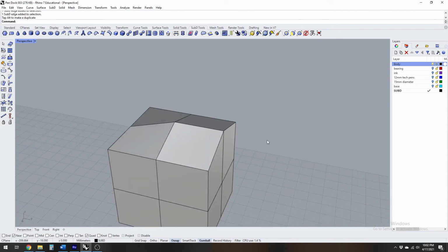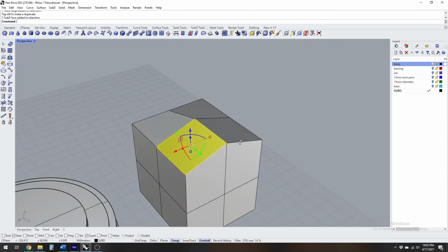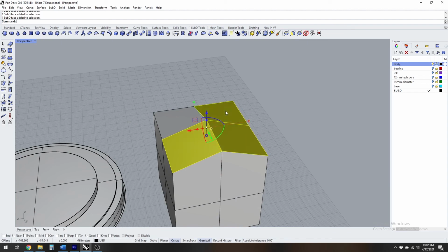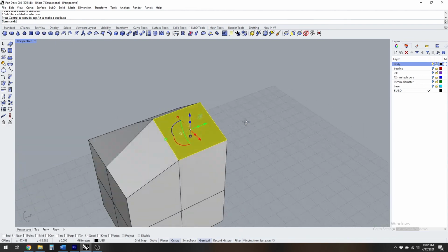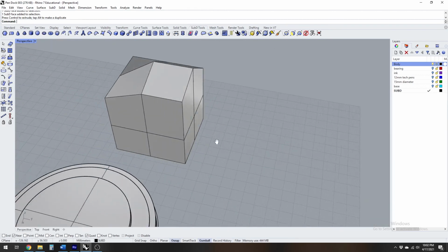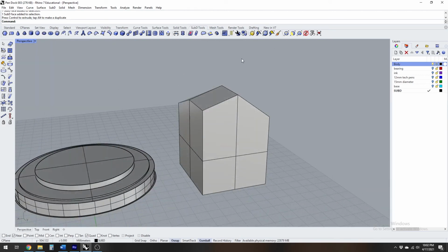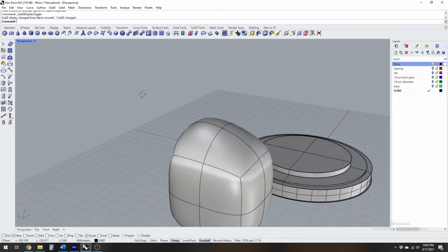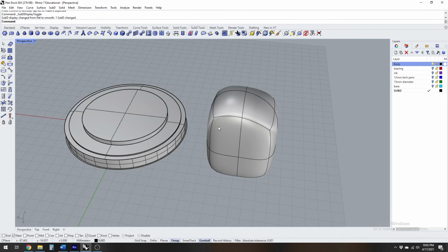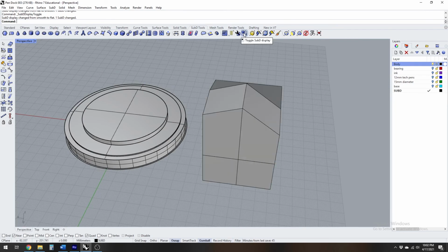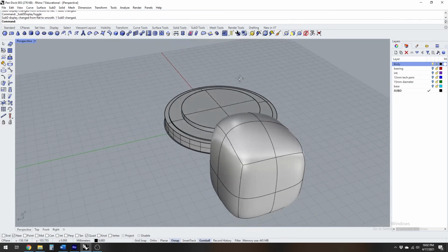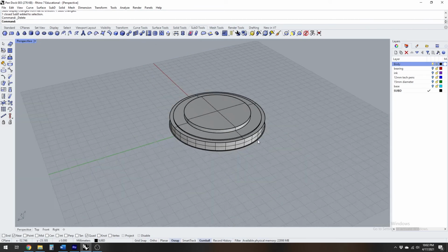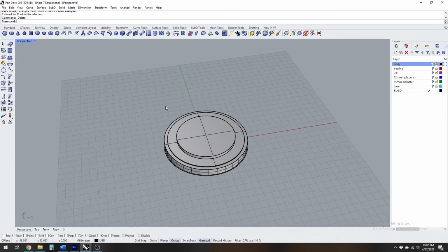While that's not super impressive, as you can see, we can select faces. What I'm doing here on the keyboard is holding down Shift and Control. This is your new hotkey when you want to work with SubD. Shift and Control allows you to select any faces as well as vertices or points for us to live transform. Then, swapping back to display mode means that we can SubD display exactly that smoothing action while still conforming to a more traditional geometry set.